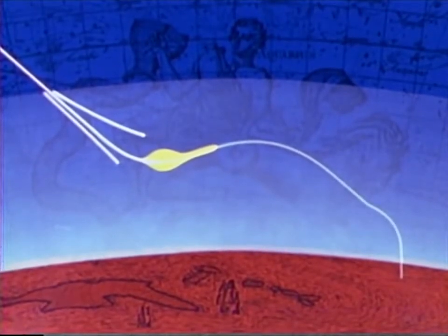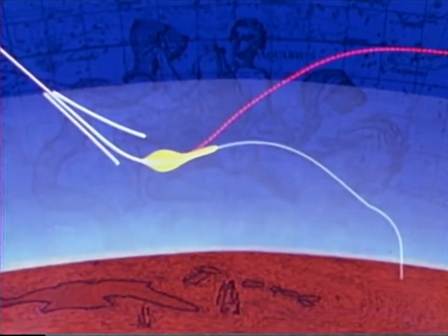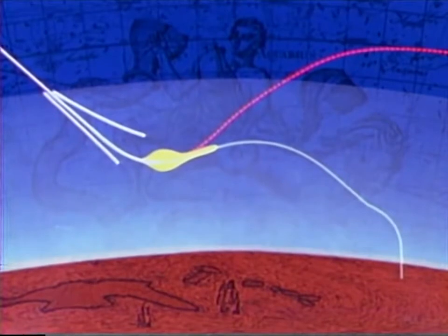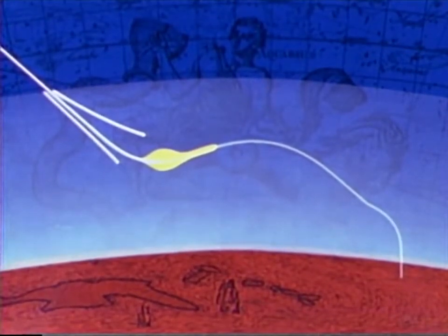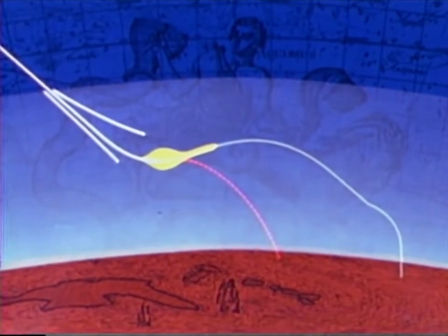That is, too much lift up could put the spacecraft and crew into an orbit that would last beyond the lifetime of the command module systems. Too much lift down could take the spacecraft and crew beyond the stress and heating rate limits and result in destruction of the command module.